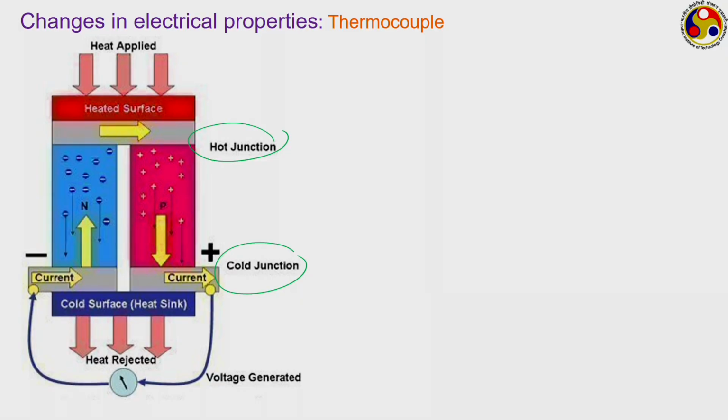And that is why thermocouples are extremely popular, because you can just take two wires of two suitable materials, and connect one end of the two wires by any common method, bridging, soldering, or just tie them with each other, and now taking them in contact with maybe a high temperature surface, you will immediately get an EMF at the other end. And once you measure that EMF, using some calibration charts etc., you can easily get the direct value of the corresponding temperature.